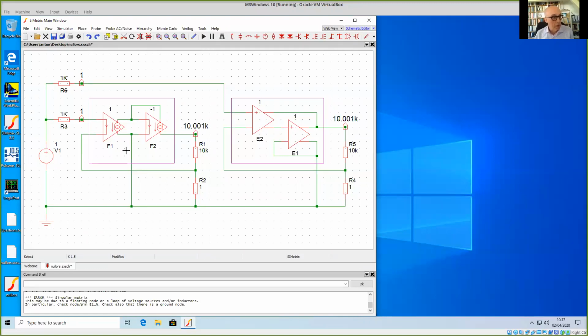And you see, I can also place here an impedance in parallel with the signal path. I can place here an impedance in series with the signal path. It doesn't matter, because voltage and current at the input are 0, and the input impedance of the nullator is undefined.